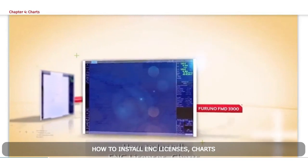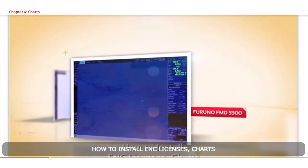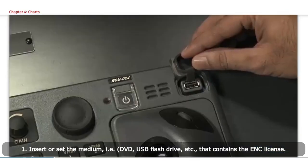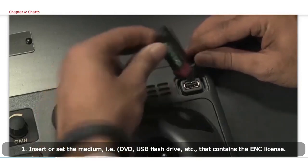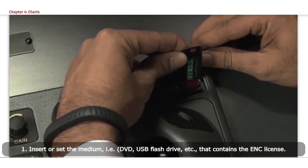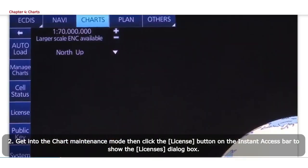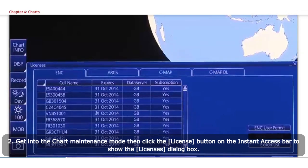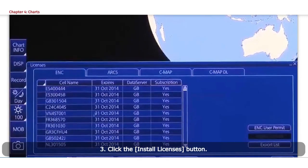How to install ENC licenses, charts. To automatically install the ENC licenses: 1. Insert or set the medium, that is, DVD, USB flash drive, etc., that contains the ENC license. 2. Get into the chart maintenance mode, then click the License button on the Instant Access bar to show the Licenses dialog box. 3. Click the Install Licenses button.